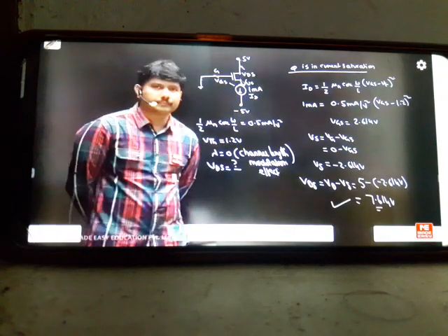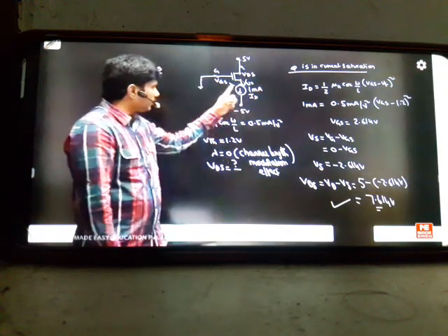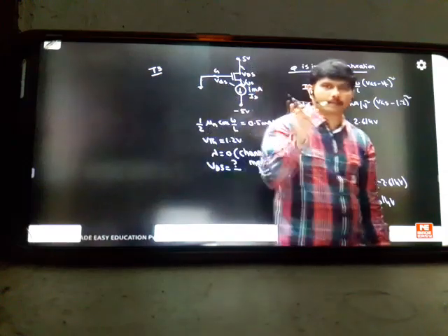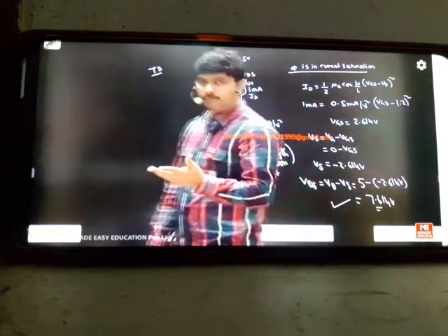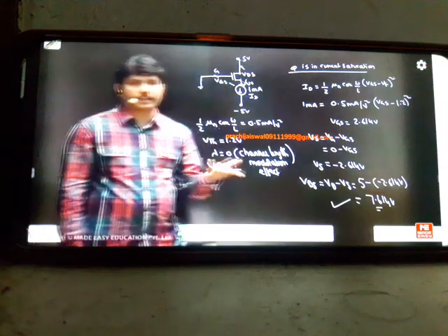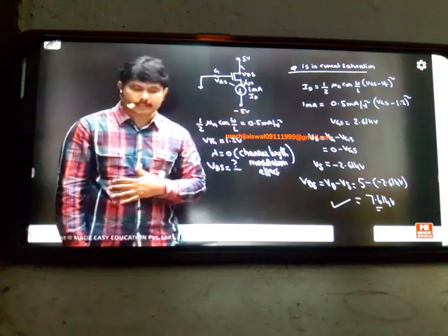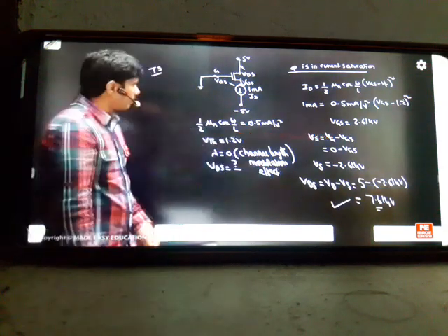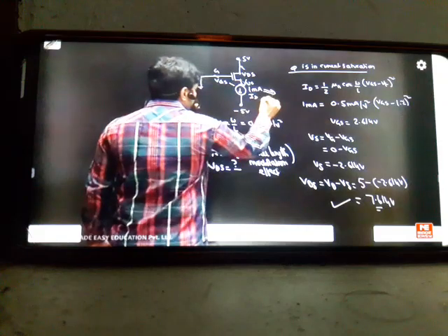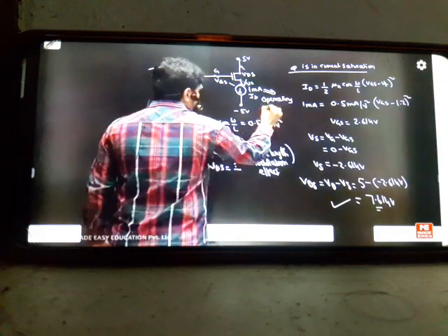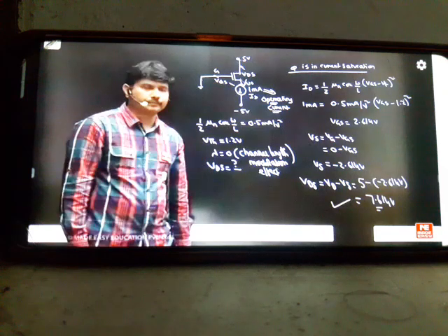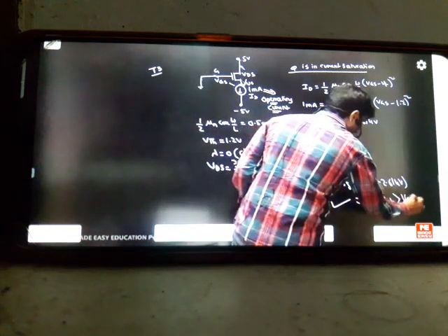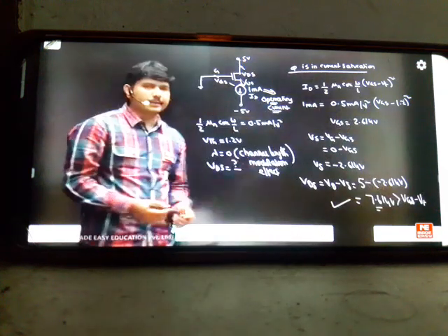We are not assuming it. Yeah, we are not assuming Q directly as current saturation because the operating current has been given directly. Whenever the operating point is given directly in the question, the transistors will compulsorily work in current saturation only. There is no need for an assumption. If you have any doubt, you can check the answer you got here, VDS, if you want. There is no problem. Definitely they will work in current saturation because the operating current is given directly. Otherwise, if you have doubt, you can verify this answer with VGS minus VT. It will be working in current saturation.